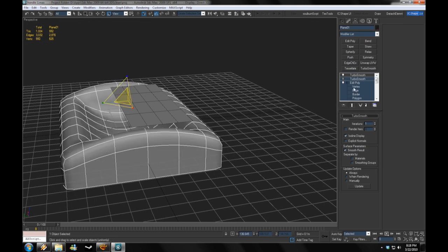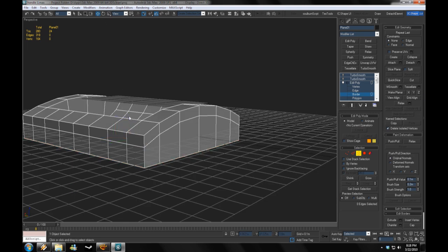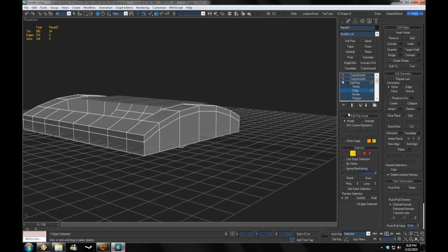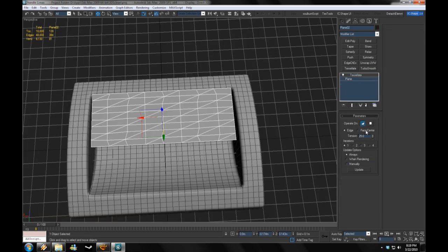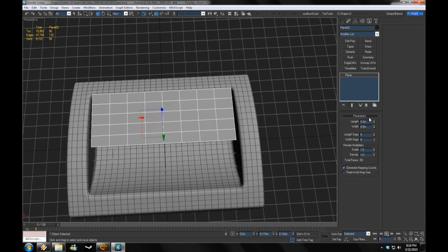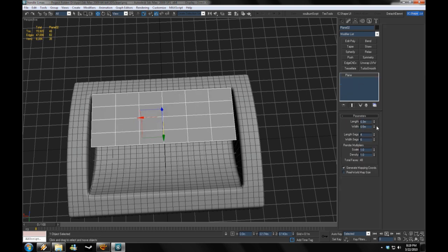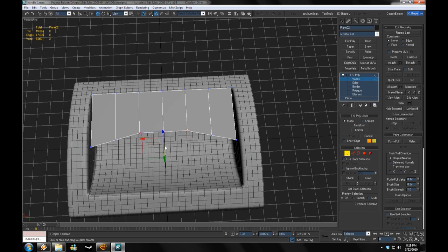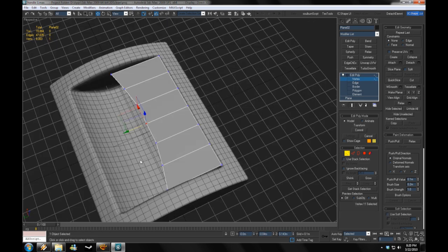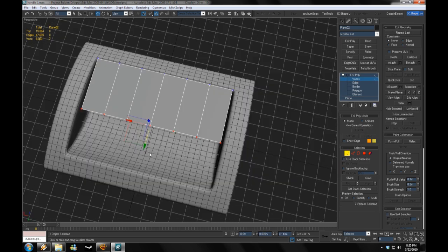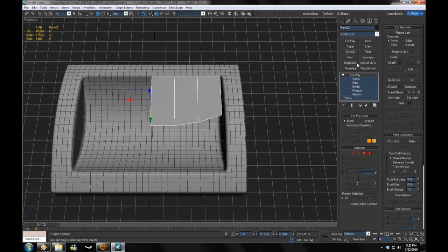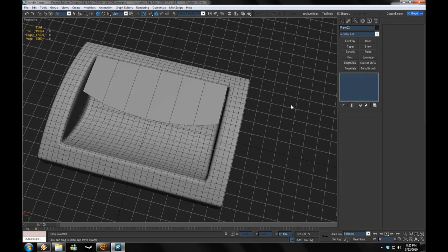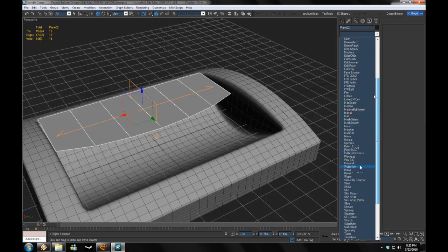And I'm just doing this by using its own plane and just modeling it on its own. And I'm going to end up using shell again, which is an extremely useful modifier. Adding more edge loops. This is kind of going to be a round handle, and I'm just going to play around with it a little bit. And that's not particularly the shape that I wanted, so I'm going to do the other way. I'm also going to make it only half. Again, use symmetry. It's a fantastic tool.